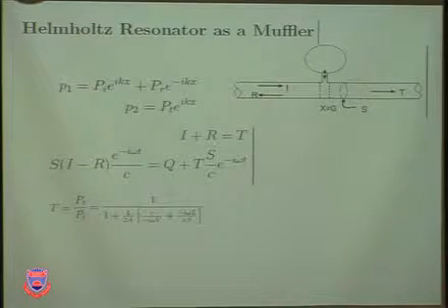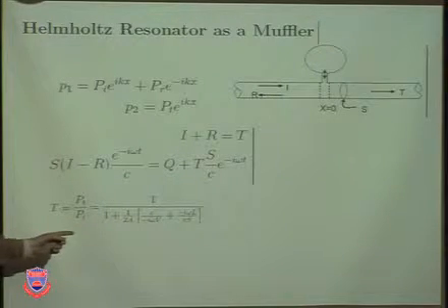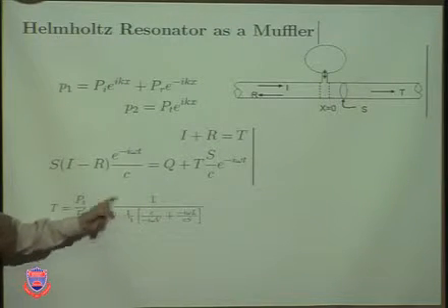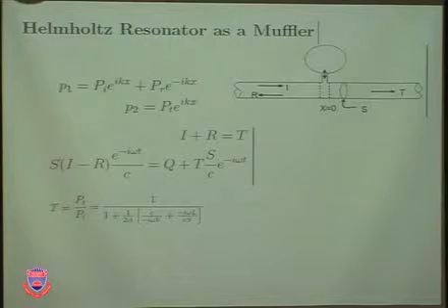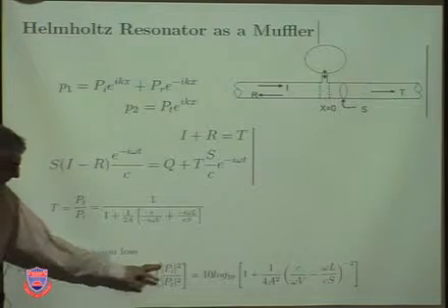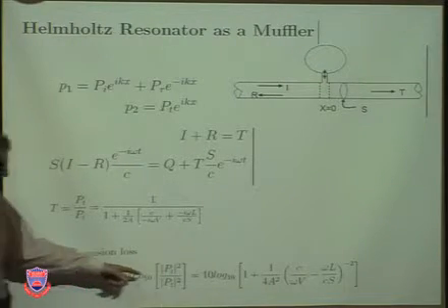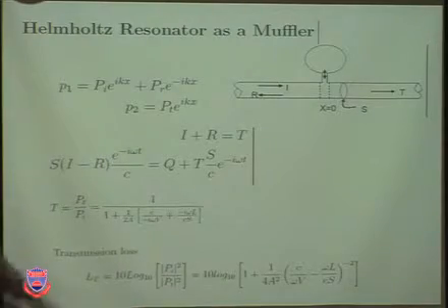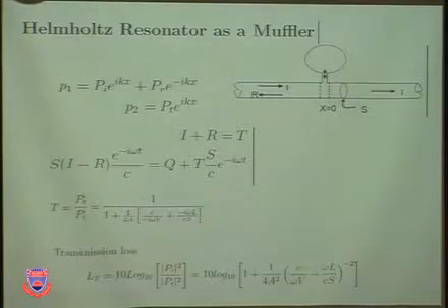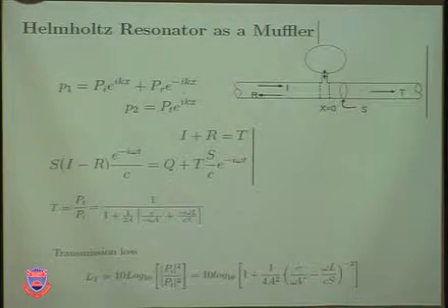And can you remember what's transmission loss? How would I write the transmission loss here? TL equals 10 log 1 over T squared. Absolute value. Very good, 10 log. So the transmission loss is the inverse of this, 10 log. You can see the expression here. Please pay attention, this is negative minus 2, so it's 1 over square of that expression.